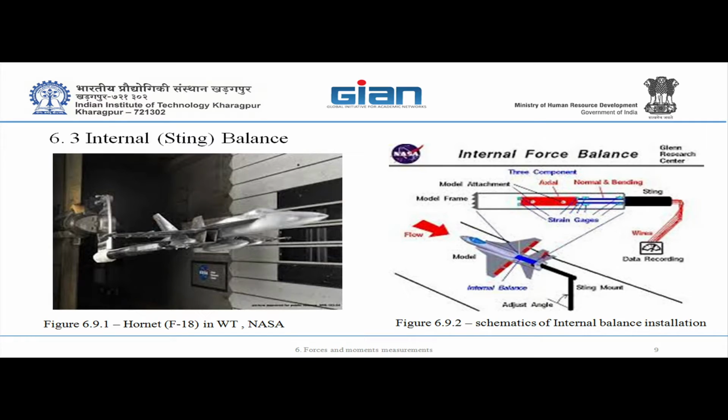Is there any criterion that the weight of the model should be this much? Now, this is a question of a beginner, but it's good. Everybody else will get it. Is the question whether there is an importance for the weight of the model? Once you are measuring the aerodynamics, it has nothing to do with the mass of the model itself. In these forces and moments, what you are worried about and taking care of is only the shape. And you make sure the shape of the model will not deform.